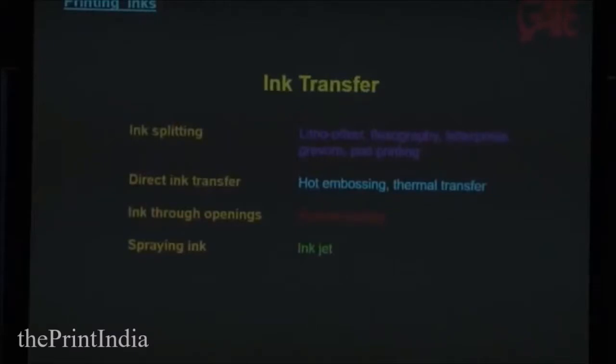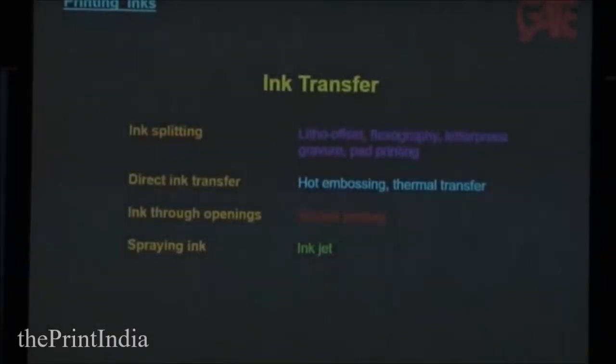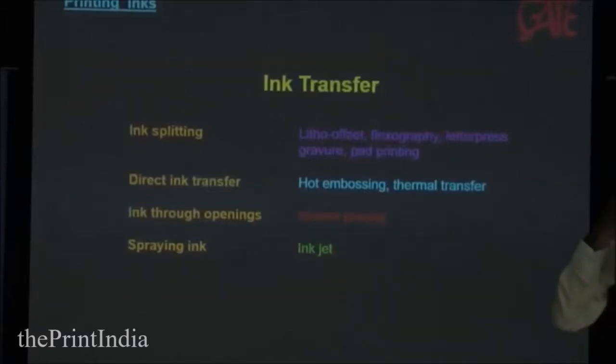Ink transfer. So depending on the process, the ink transfer process changes. Ink splitting. In litho offset, UV flexo, letterpress, UV gravure, pad printing, the ink is transferred from one roller to another roller or to the substrate by splitting the ink. Ink is split into two and half the portion is transferred.